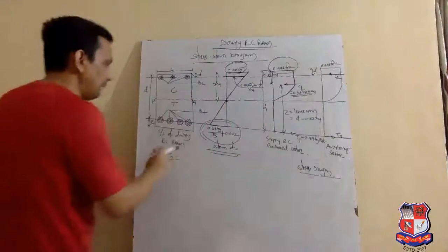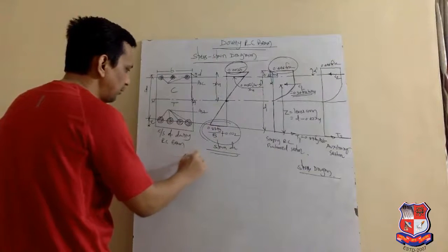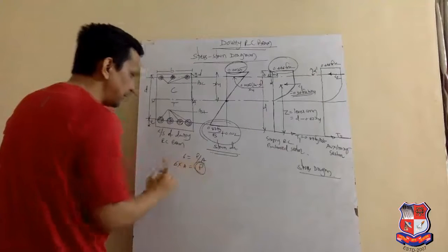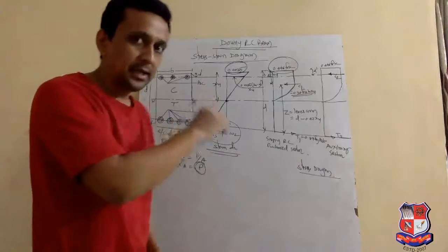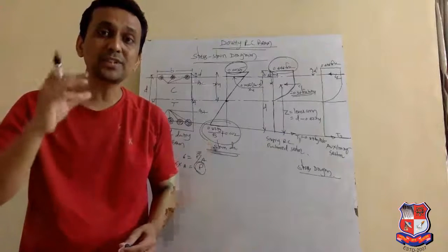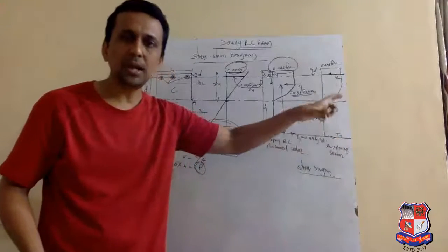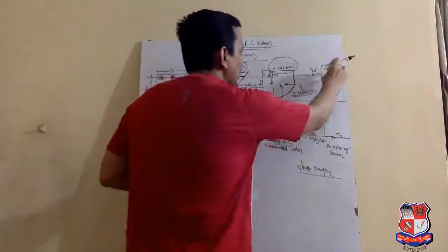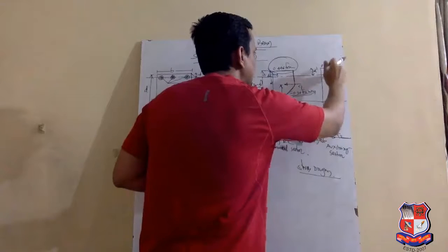Again, if we want to find the value of C2, stress sigma is equal to P by A, so sigma into A equals P. Our interest is P. What is sigma? Here 0.446 fck is the maximum compressive stress in concrete. But this auxiliary section is all about the compression reinforcement, so what is the stress in this compression reinforcement at the level of d dash?